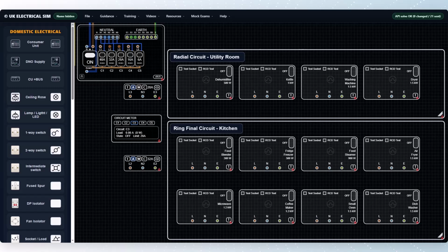In this video we're going to look at the difference between a radial circuit and a ring final circuit, explain where they came from, where they are commonly used, and the typical protective devices used for each type. A radial circuit starts at the consumer unit and runs out to the final point in one direction only, whereas a ring final circuit starts at the consumer unit, but it continues around the circuit and returns back to the same protective device, forming a complete ring.